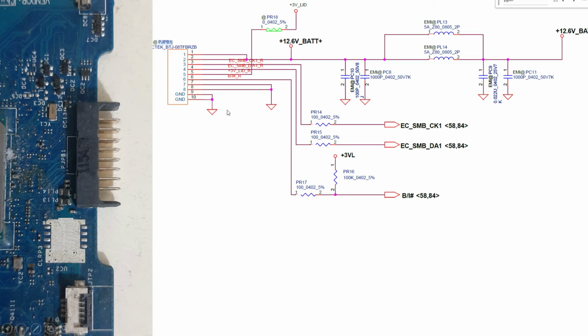So here are the battery circuits. How does it look, what pins are there? Here also almost 8 pins are there. See, first and second are the red wire. So directly it goes to the L inductor. After that it purifies and becomes 12.6 volts bat. It means before and after, two capacitors are there. This is for filtering, I already explained to you.